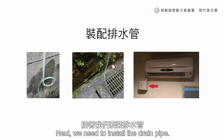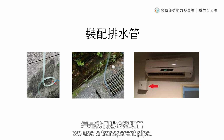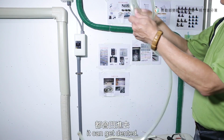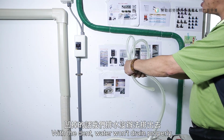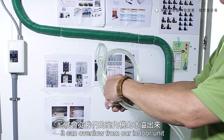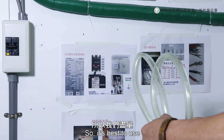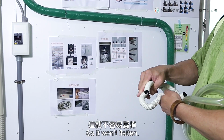Next, we need to install the drain pipe. When installing the drain pipe, we use a transparent pipe. Sometimes when we install it, it gets dented. It can get deformed. With the dent, water won't drain properly. It can overflow from our indoor unit into the room. So it's best to use a more resilient type of pipe like this so it won't flatten.